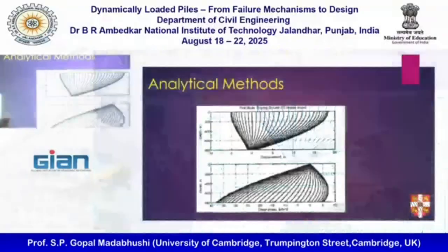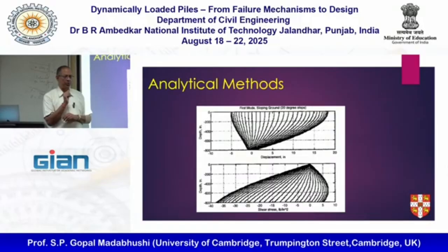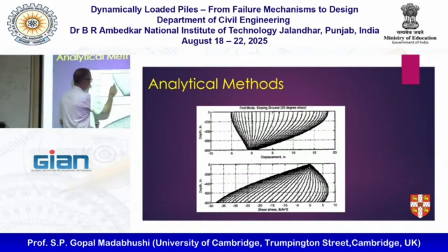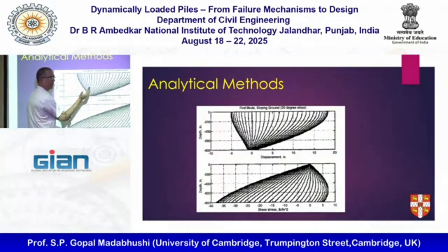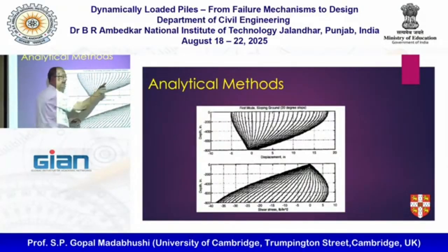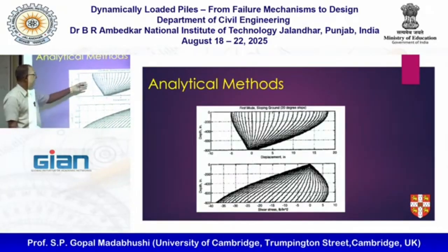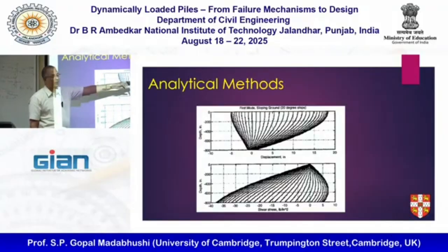And what it is saying is, when you shake it, what is the mode shape it will go to. So it can start somewhere going upslope here, like this, to downslope there. So cycle by cycle, I can accumulate movement towards the downslope. Okay, so if I have 10, 15 cycles, I can accumulate quite a lot of displacement cycle by cycle.